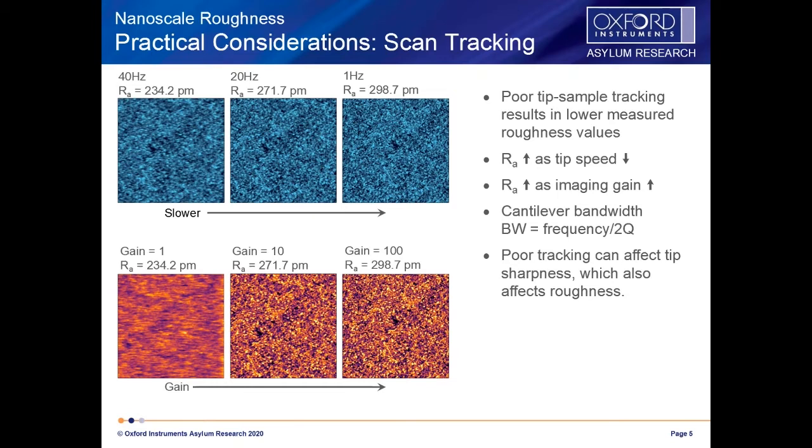The other thing to keep in mind is the gain of the feedback loop. So when you receive AFM training from the staff at the UT Dallas Clean Room facility, they are going to explain to you how an AFM works. And there is a parameter called gain, which is part of a feedback loop. If you set the gain of the AFM to be too low, then you will not track the surface. And if you don't track the surface, your numbers are going to be inaccurate. So you need to make sure that the gains are set up correctly.